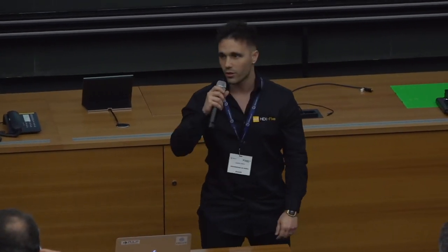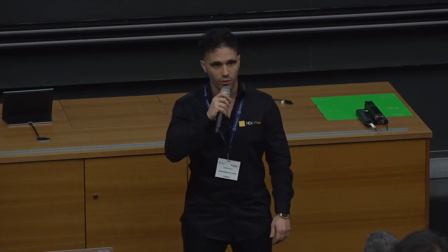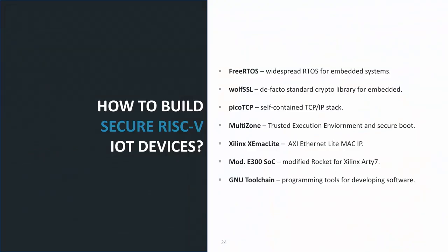My name is Sandra Pinto. I'm from University of Minho in Portugal, and this work was done in cooperation with RISC-V. This basically describes the first fully functional software stack for developing secure RISC-V architectures, and we are using MultiZone as the underlying infrastructure for providing multiple isolated execution environments. On top of MultiZone, we run several software components: a secure version of FreeRTOS, a secure TCP/IP stack, PicoTCP, and an embedded crypto library, wolfSSL.